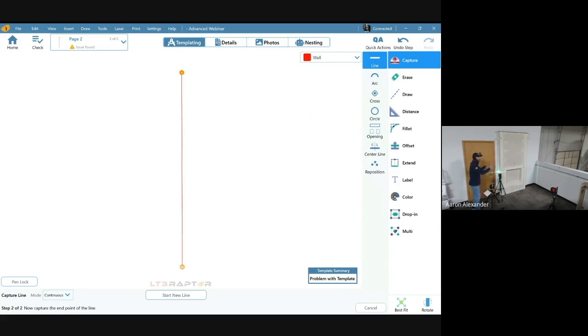And again, I'm shooting the back wall now because we're creating the plane in space as this edge. But when it comes to templating, measuring here, we created our plane there, which is what our stone's going to be glued to. But then what are the boundary objects that create that shape in space? So the back wall here creates one edge we want to bump up against. So we're going to shoot all our points for the back wall on the wall itself, no more than a half inch away from that edge returning into it.